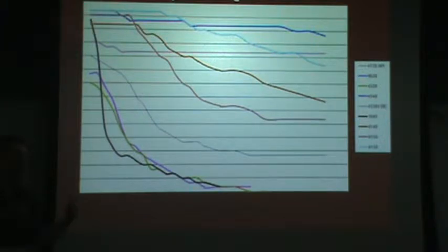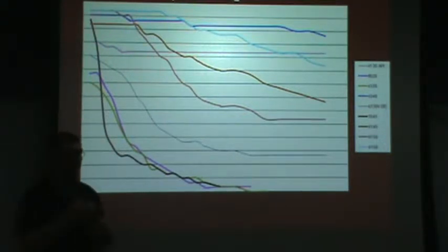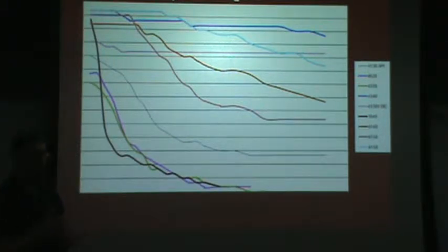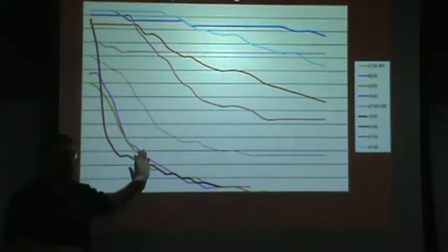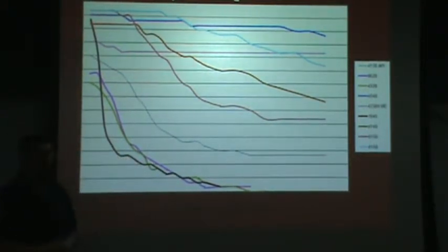So they then show you in the Jominy hardness requirements both the upper and lower limits for the hardenability based on the typical range of elements for those grades, right? So I've only shown a single curve for each one based on results that we had in our history and our data work. But if you were to go and look somewhere, to see what's typical, you would see it expressed as some lower curve and some upper curve.